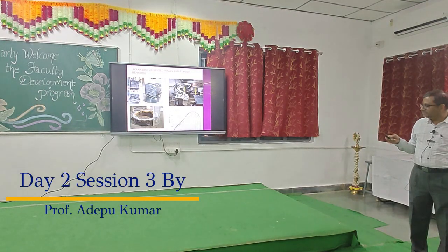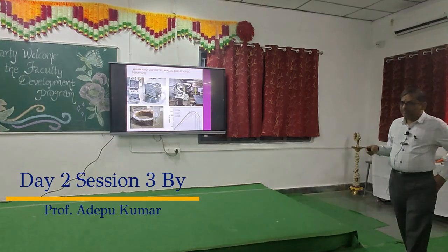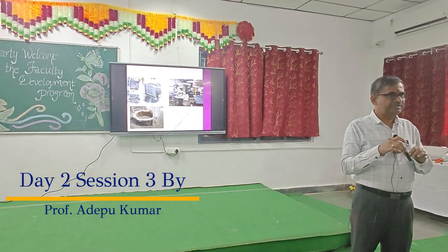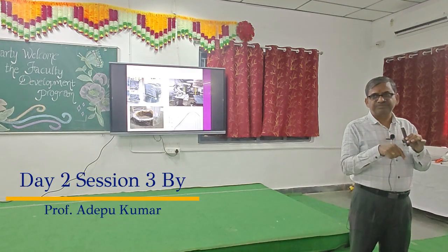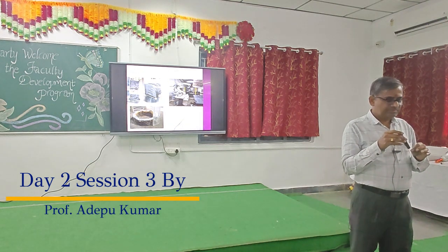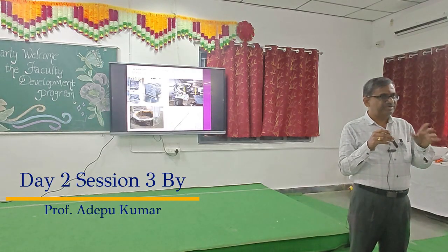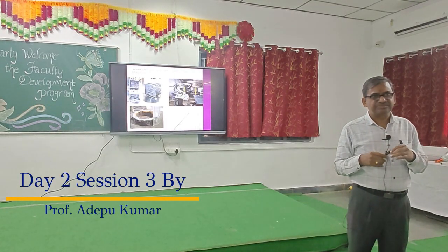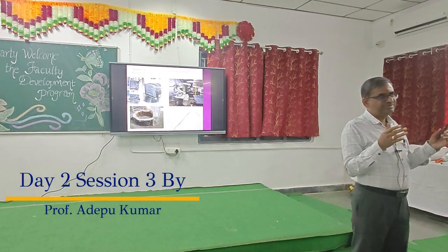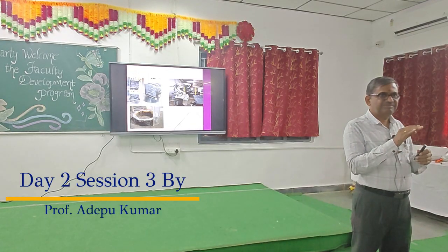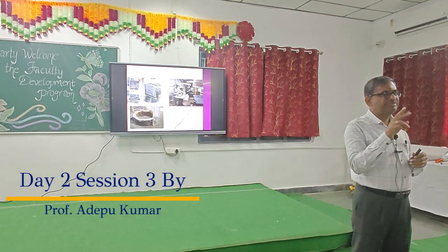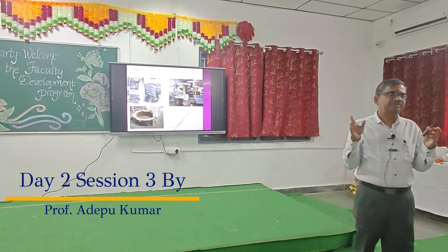This synchro feed, what does it do? In the normal welding process, you are melting the material and continuously feeding the wire downward, right? Some technology is cold metal transfer welding. Have you heard of this word? What does it mean? It is the same as your MIG welding process. There is no difference in the deposition of the material, the gun and other parts. The only difference is in the power circuit.